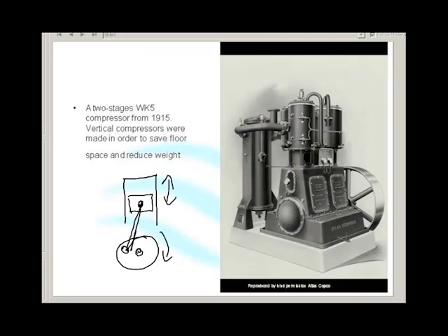What we always have to ask ourselves about compressors is, what do we do with the compressor when we've reached enough air, when there's enough air pressure? This is a type of compressor you might go out to somewhere like Bunnings and buy a small one. With a Bunnings compressor, a small one, when it gets up to pressure, a pressure switch just switches it off. With this type of compressor, why do you suppose we can't just switch it off when we've got to pressure and switch it back on when we need more pressure?